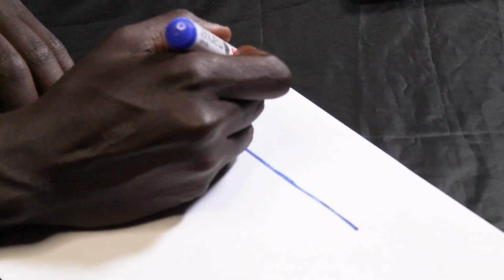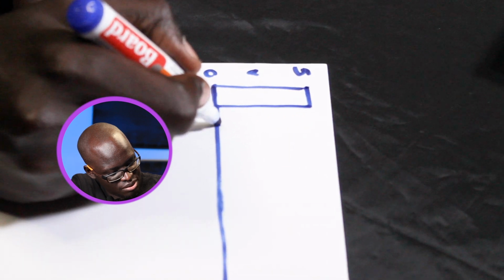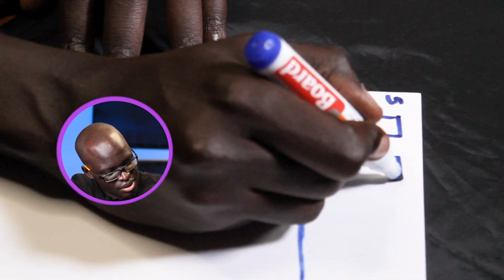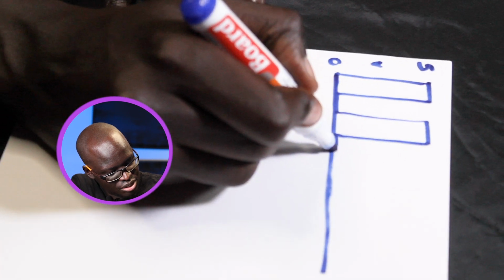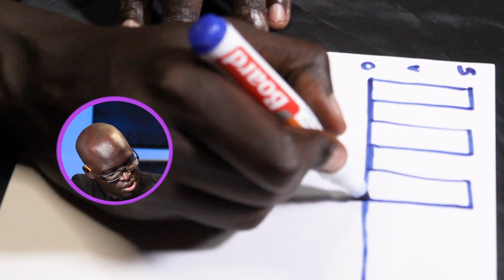When it's up here, you're getting a voltage of 5, which is the maximum. The way PWM works is that it sends a series of signals, and how those signals are structured is called a duty cycle. For example, if you remember our LED blinking on and off, it sends a signal to turn on at maximum, then turn it off, then turn it on, maximum, turn it off, like that.